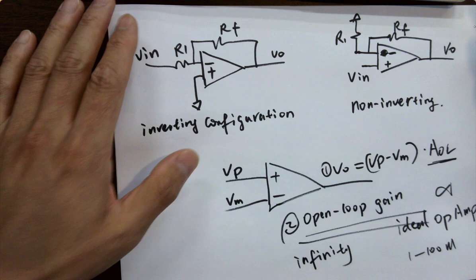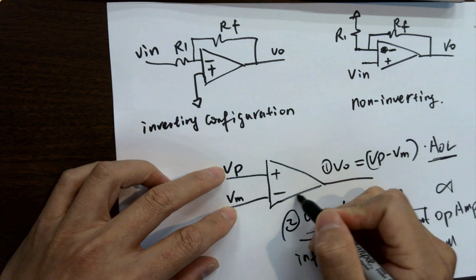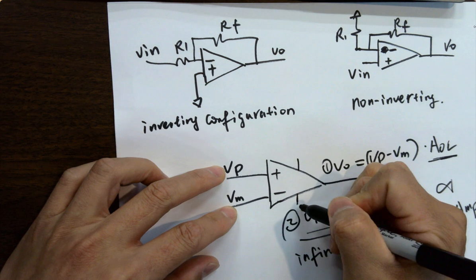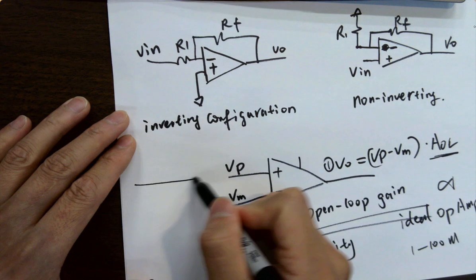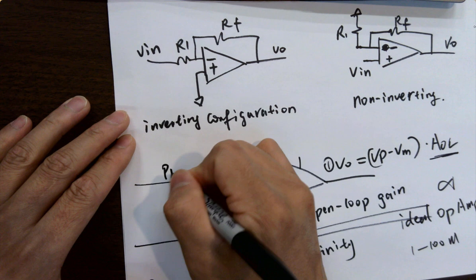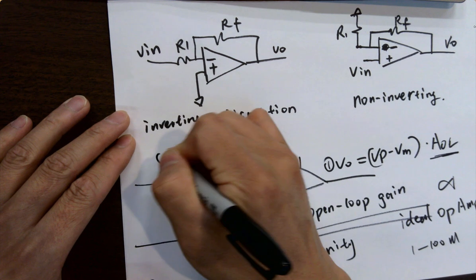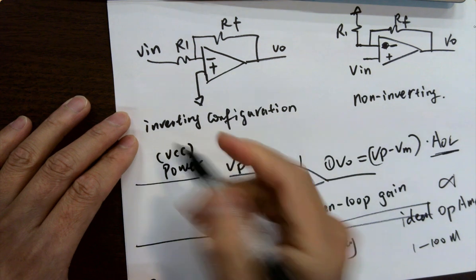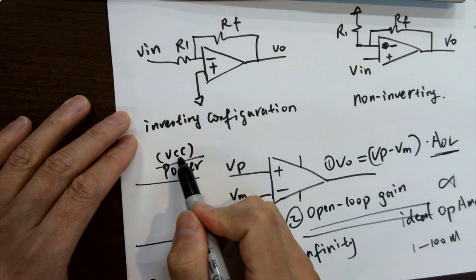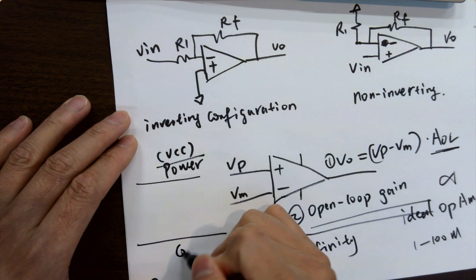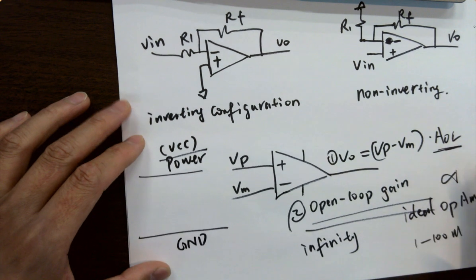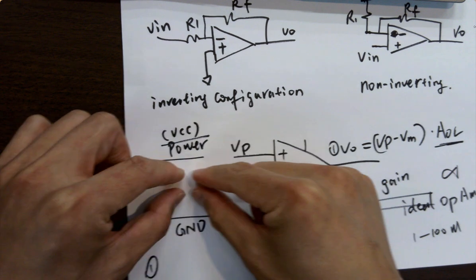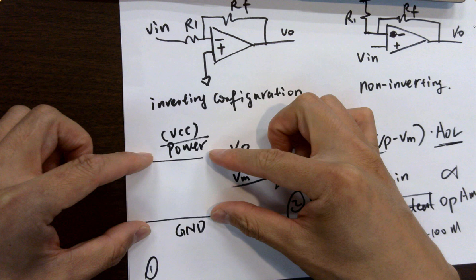Yeah. So if you have higher here, it's going to be a negative voltage depending on your upper and bottom rails. The rails mean the power rails. It's the power on the top, usually labeled as VCC. It's a collector with the BJT transistors. This is too much, but let's just remember it's usually labeled as VCC or VDD as a power and GND as a ground. So you build your circuits within the two rails. These are called power rails.